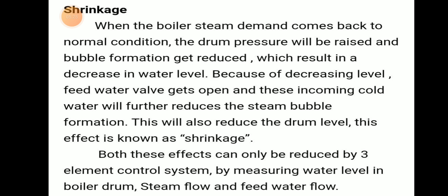This means when boiler steam demand comes back to normal condition, drum pressure will be raised and bubble formation is reduced, resulting in a decrease in the water level. Because of the decrease in water level, the feed water valve opens, and this incoming cold water will further reduce the steam bubble formation. This effect is known as shrinkage. Both shrinkage and swelling can be reduced by a 3-element control system, by measuring the water level in the boiler drum, steam flow and feed water flow.